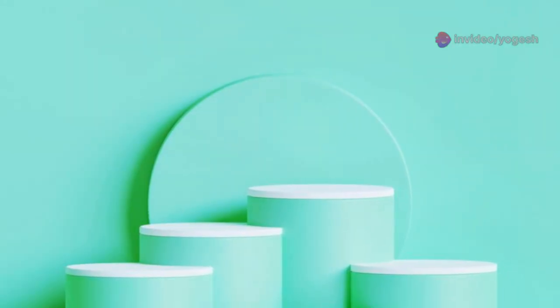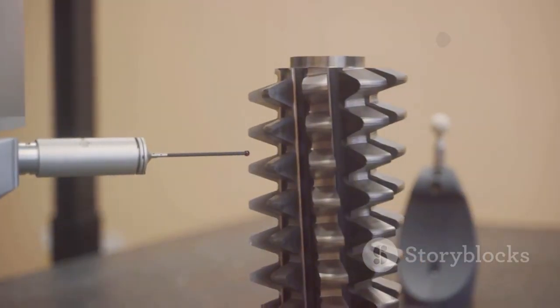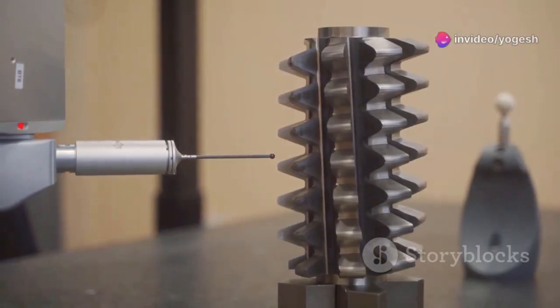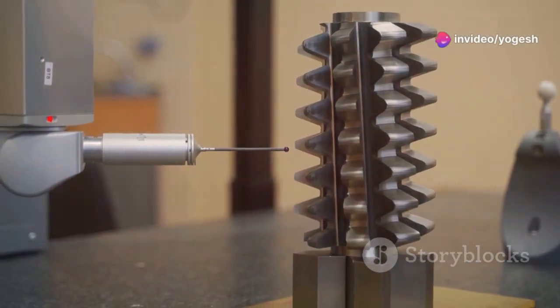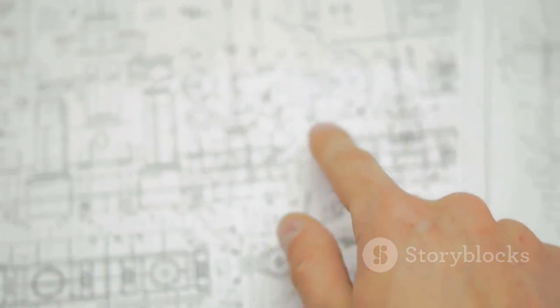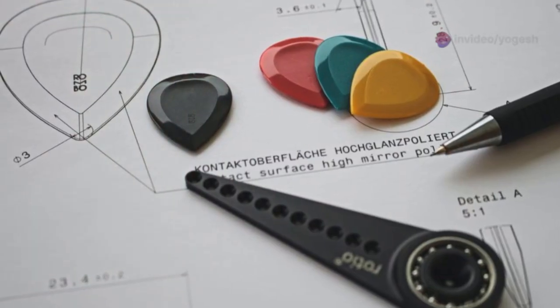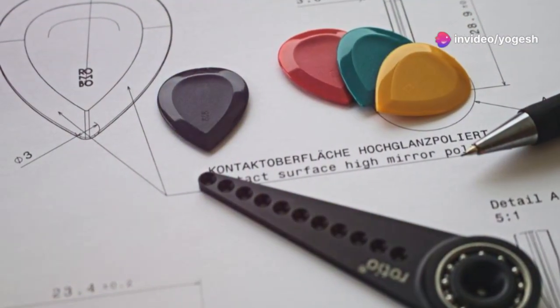The second compartment gives the tolerance zone, a cylinder centered on the datum axis with a specified diameter. For example, 0.05 means the axis must stay within a 0.05 millimeter diameter cylinder. The third compartment names the datum, the reference axis everything aligns to. If you see datum A, look for the feature labeled A elsewhere on the drawing.